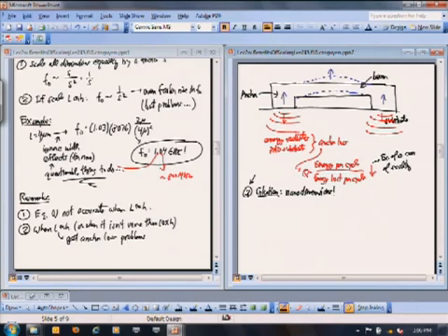4 microns. Right? It turns out that to get to gigahertz frequencies, you'll have to scale L to about 1 micron long, but the thickness of the beam is going to be on the order of 300 nanometers or something. Okay, so you're at the nanoscale, not quite nanoscale in length, it's still about 1 micron long. It's 1,000 nanometers if you want to call that nanoscale. But it turns out if you do that, you will get frequencies on the order of gigahertz, and you'll do it with respectable Q. Okay, so that's one way to do it. This is one good way.